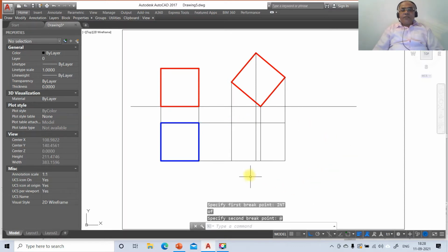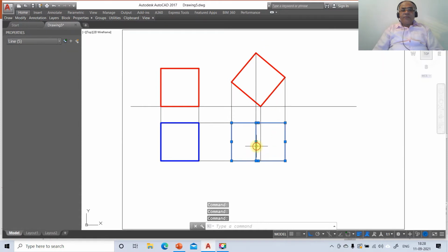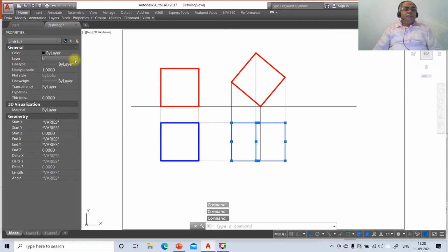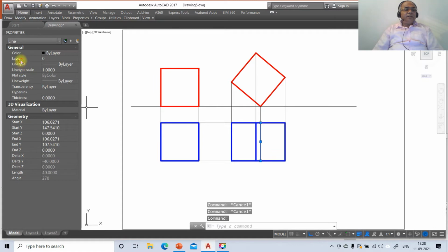Now once you have this, you select all the exterior edges. The boundaries of the solids are visible and the surface nearer to the observer is visible. So this will be visible. So you take that as top view, and the edge which is on the XY line is always invisible in the top view. So you take a top view hidden and you make that distance as 20.